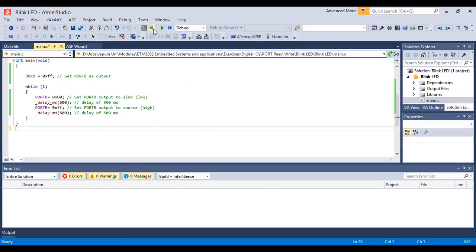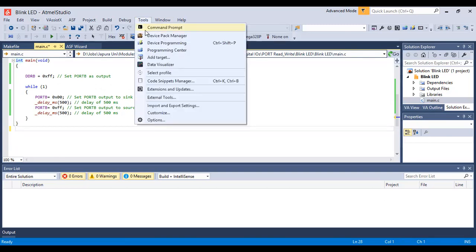If you use real hardware, you just plug the programmer to the USB port and the other end to the microcontroller and go to device programming. Actually I can't remember exactly, but once you plug it in, it will by default show the programmer that you have used here. Then you pick that programmer and go to device programming, and it will detect the programmer and the microcontroller itself. If the microcontroller is healthy, it shows that it is healthy. Then you can just burn the code.